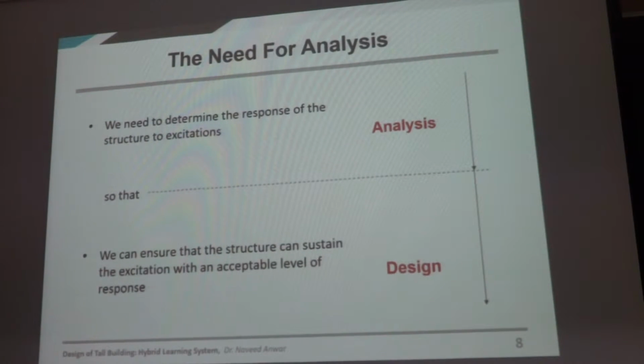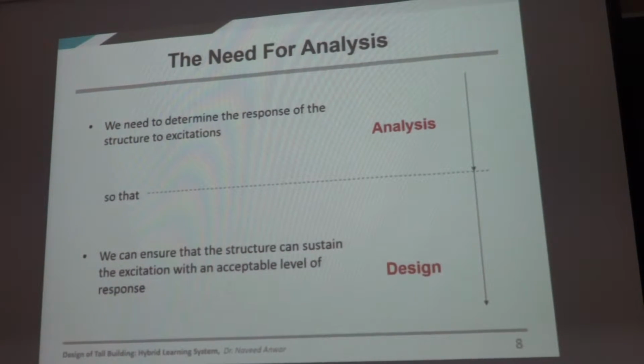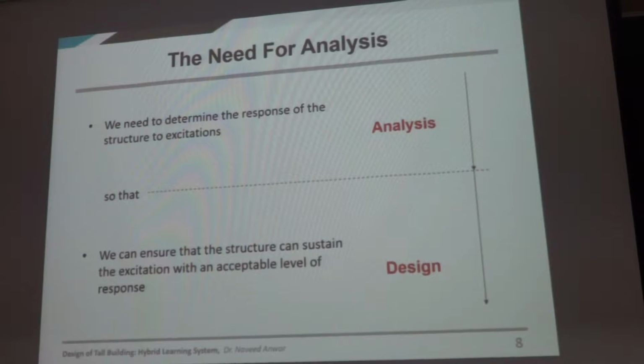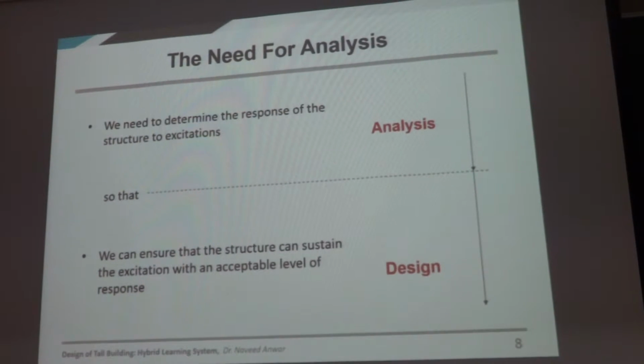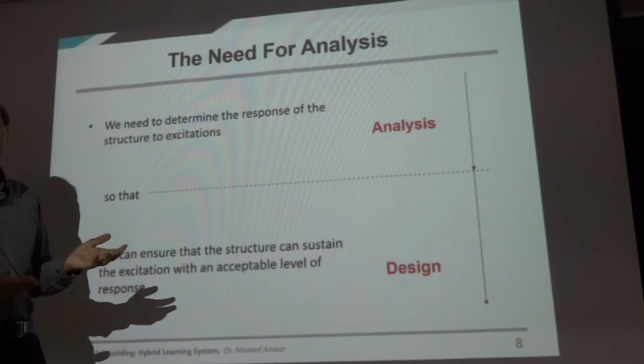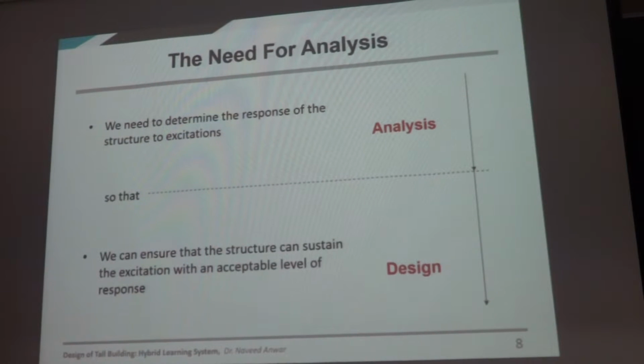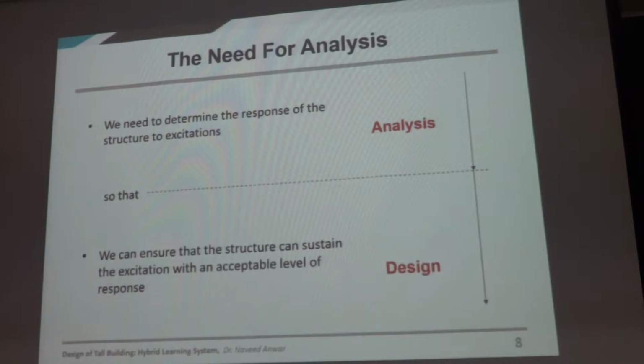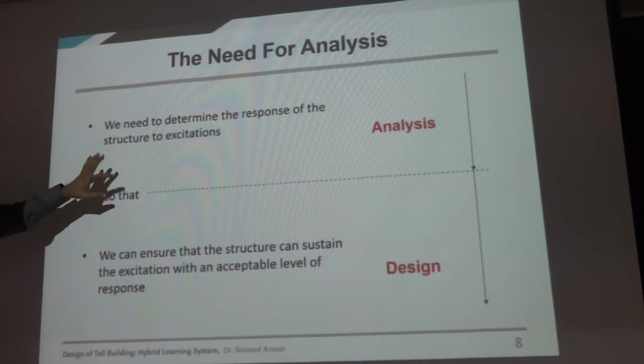So you can calculate the response of anything, whether it is going to work or it doesn't. Like for example, I told you, you can calculate the displacement for 1 million ton, which will come out to be 1 million centimeter. But that is not design. Design will not allow you to do that. Design will say, oh, no. You cannot have more than 4 centimeter displacement for this frame. So stop. So analysis can give you any number, acceptable or not acceptable. But design makes sure that it is acceptable. So design and analysis always go hand in hand.